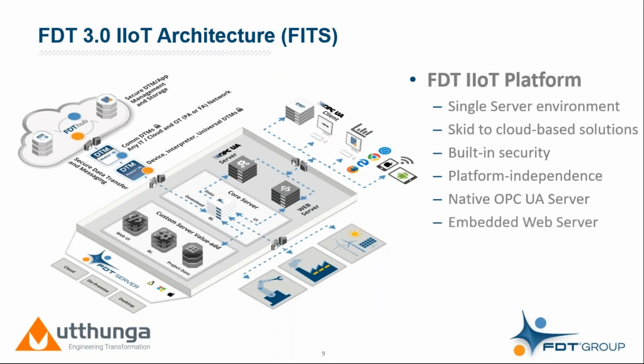We also have the embedded web server that's automatically a part of any FDT server. This is how you access both the information and the graphical user interface of the FDT installation. So where in the past you might have looked on a desktop to configure a device or troubleshoot a device or configure a network or look at network loading, those types of things, you can now do that remotely through that embedded web server.